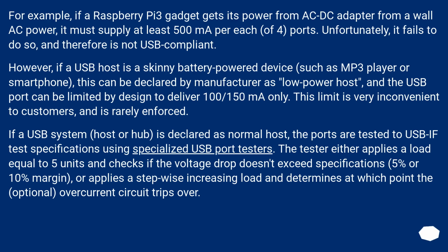However, if a USB host is a skinny battery-powered device, such as an MP3 player or smartphone, this can be declared by the manufacturer as a low-power host, and the USB port can be limited by design to deliver 100-150 mA only. This limit is very inconvenient to customers, and is rarely enforced.